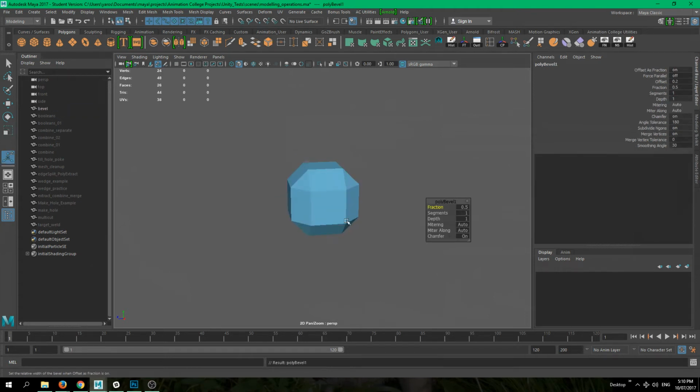So if we click on it, and you saw that we had the whole object selected, so we were in the object mode. It gives us this result, so we can control the amount of bevel with Control, clicking on the fraction word over here. So I'm pressing and holding Control just to get a smoother result when I'm doing this.